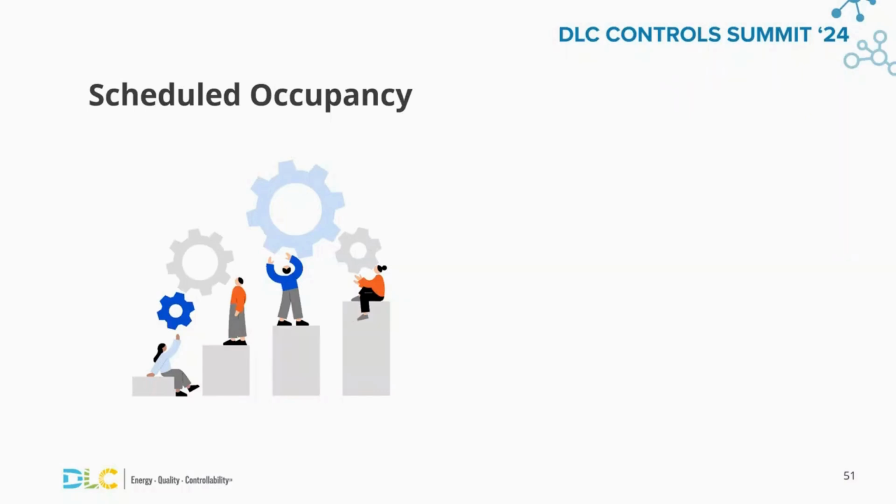In some commercial buildings, activities run like clockwork. The facility manager knows exactly when each space needs to be conditioned, and they always schedule the HVAC system to run when it's needed and not when it's not. In a building like that, occupied standby mode will not save enough energy to be worth the trouble.